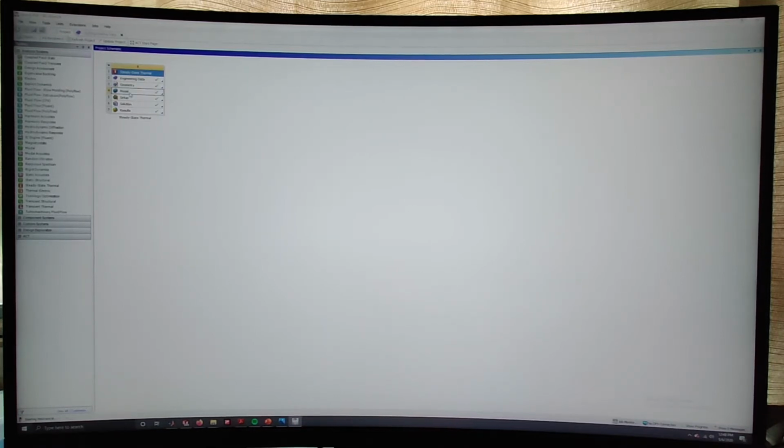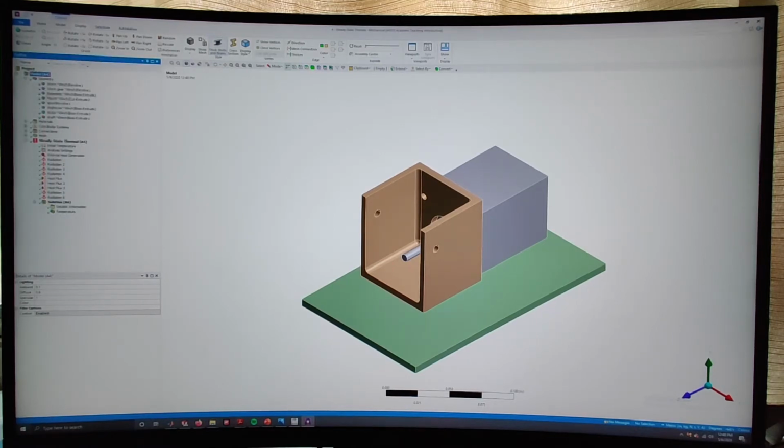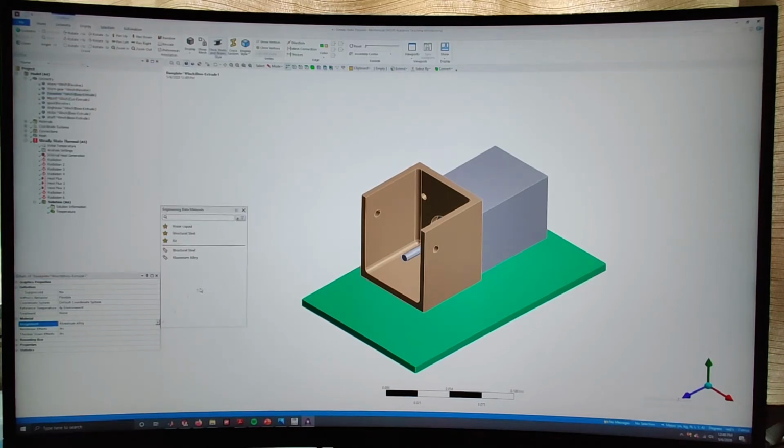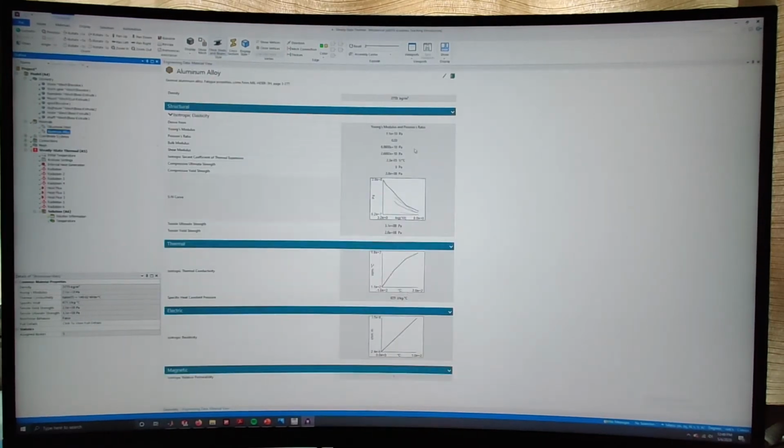Alright, and then we are going to jump over to our model. That'll pull up ANSYS Mechanical. So here's our geometry. You can see, it's what we just talked about. Here I've just suppressed these parts that I'm not interested in worrying about. But for everything else, the material will just automatically be structural steel, so you'll have to set that to whatever you want it to be. You can just click on it, structural steel, or jump back to aluminum. No problem. Run through all those materials, you'll see you can get more information about what they're actually using. And then aluminum's the one I pulled in.